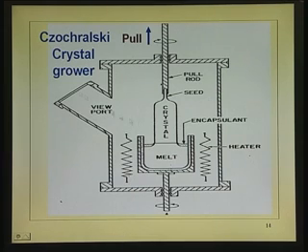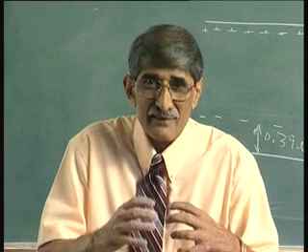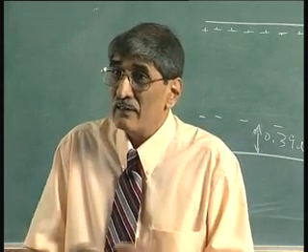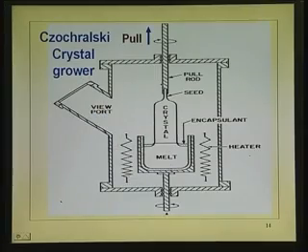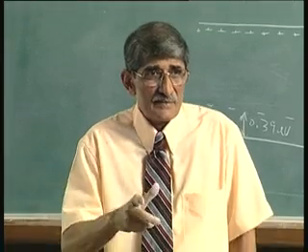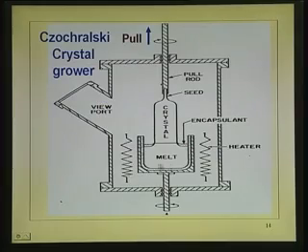This is where the crystal grower views how it is growing, whether it is going all right, whether you are having any pinning, twisting, etc. taking place. This should all be done on a vibration-free table, because the slightest tap will give twins, defects, in the crystal to twist. So, that is the growing of gallium arsenide from the melt, and the system should withstand that high pressure. And you can see this is the heater, it can be resistive heating or RF heating, either way you can use it.